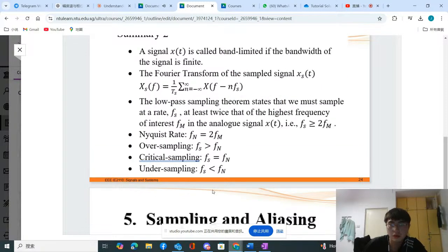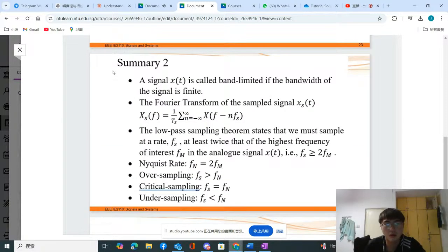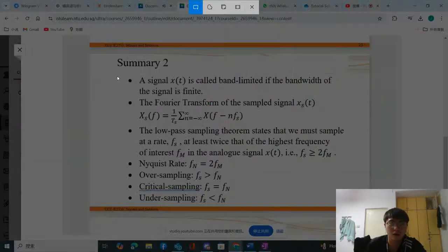For the third case, when you sample at less than the Nyquist rate, we're going to result in fewer samples being generated, but with aliasing happening, okay, which is actually not good because in this case, you will not be able to recover the original baseband signal.